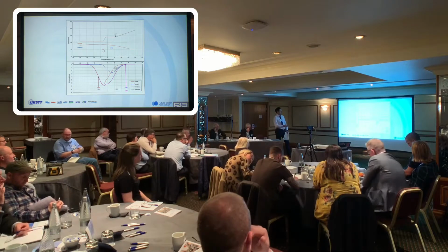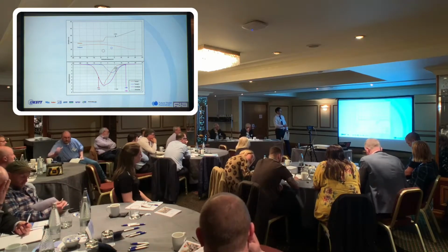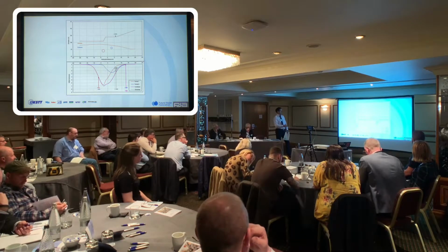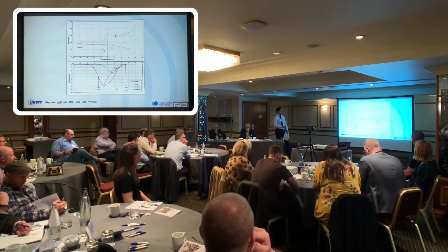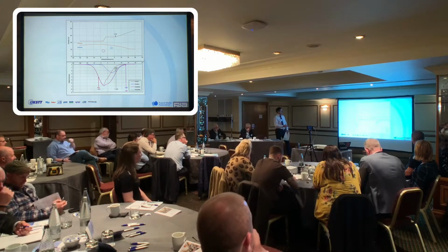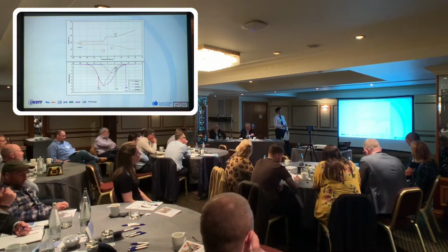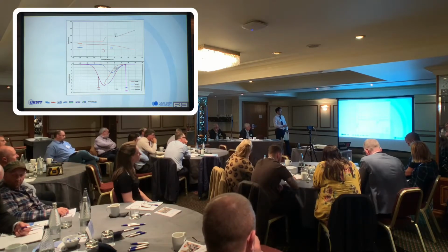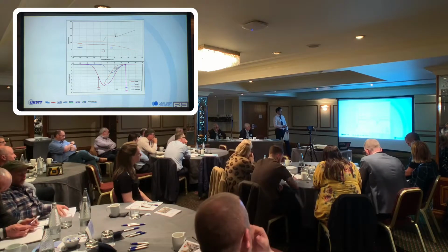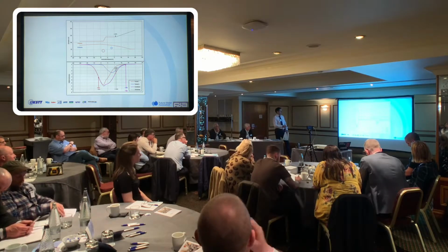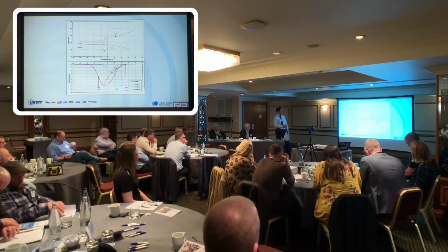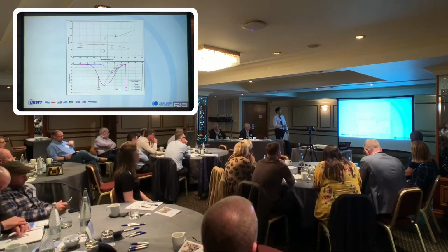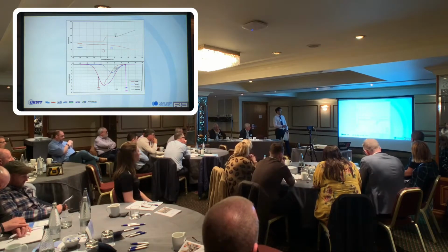Again, showing a varied ground profile where you've got two drives as well. The larger diameter is going to govern the maximum settlement, and this happens to have probably the worst case, where you've got the larger diameter drive with the shallowest cover, and a bit more cover on the smaller drive. That's the big hit, so that'll be the main sticking point, and then we'll have to try and get that to work.